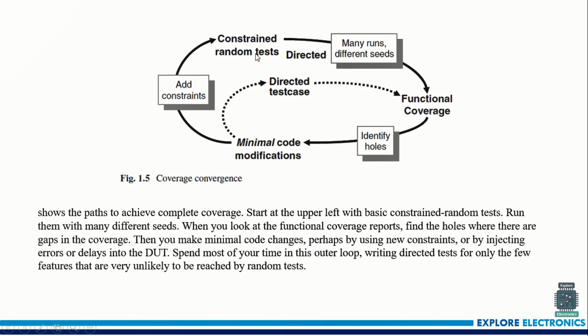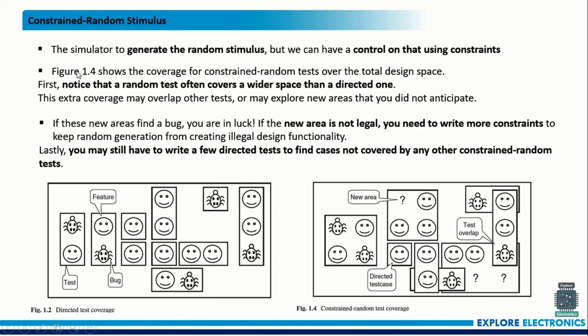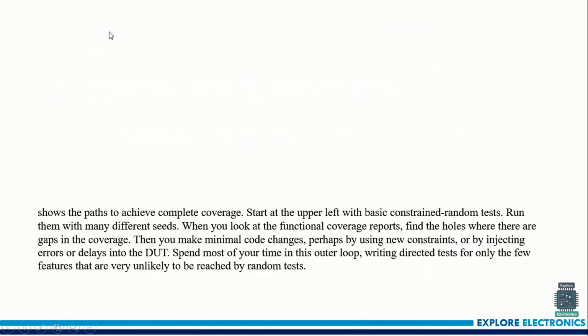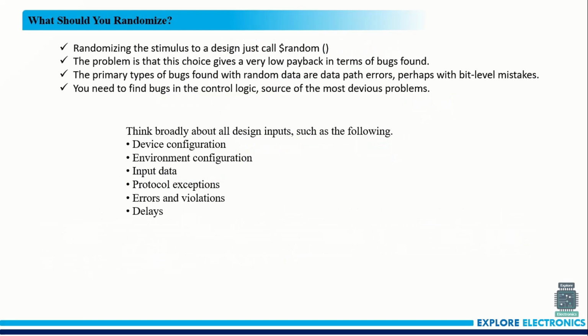But if you have constrained random values and we also change the seeds, the values generated are going to change and be given as new values, and we'll achieve the functional coverage very soon, we can say. So this is about the coverage and the advantage of going with constrained random stimulus other than direct values, right?